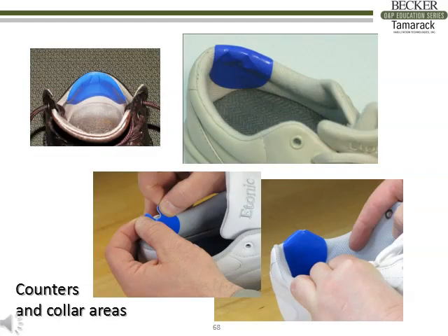As noted earlier, make sure that the surface is clean and dry. It helps to dry run the placement in any application. Then peel the release liner away from the patch to expose the sticky pressure-sensitive adhesive, PSA. Avoid touching the PSA with your fingers and use your best aim as you place the patch into the correct location on the first try. It is possible to pull it off if you haven't set the patch, and retry if you need.